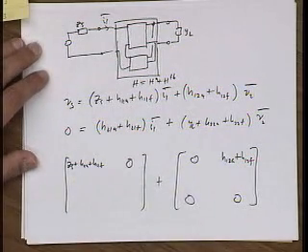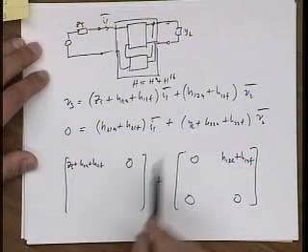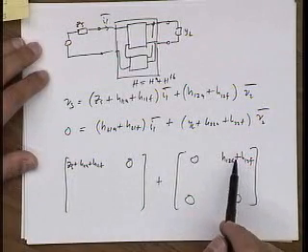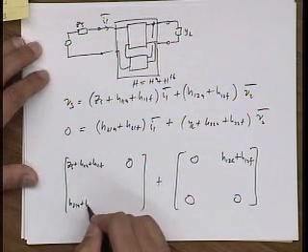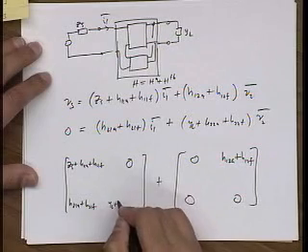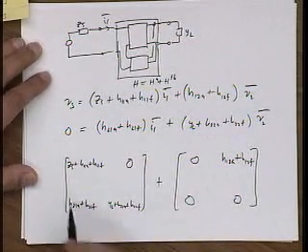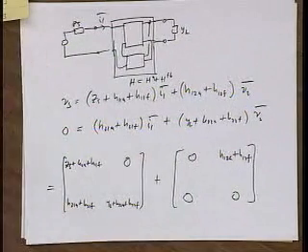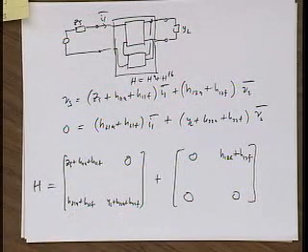Here I put 0 because I'm taking all of this term and lumping it in here. Remember, that's the feedback term. So I'm putting the feedback term here. H21 amplifier plus H21 of the feedback network. And then finally, YL, H22 amplifier plus H22 feedback. Okay, why did I do that? Why partition it in this way as opposed to the real physical way?